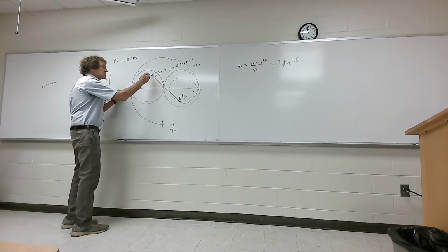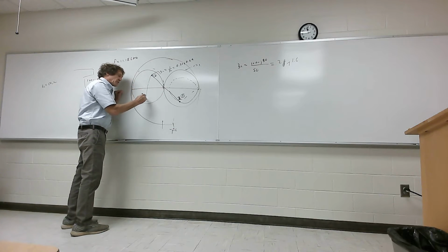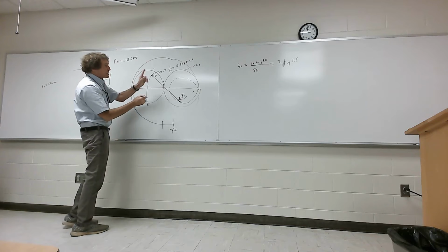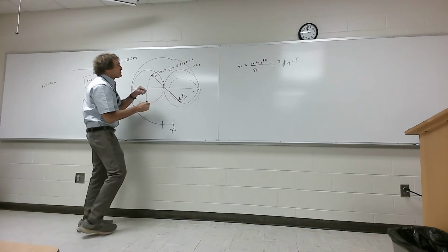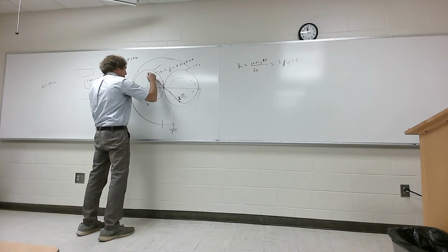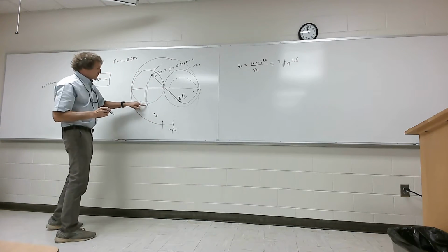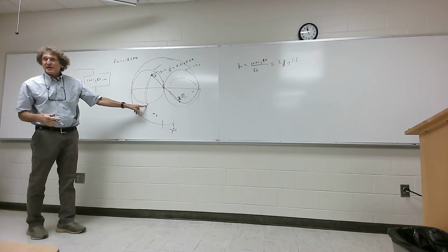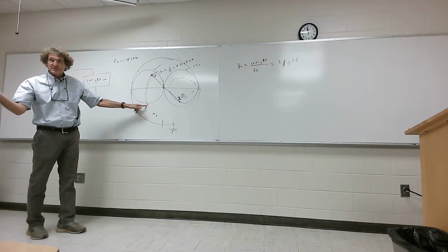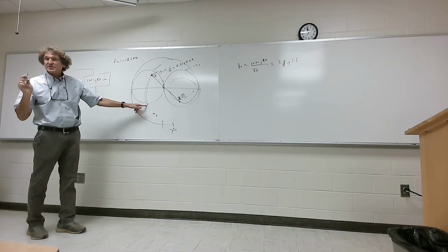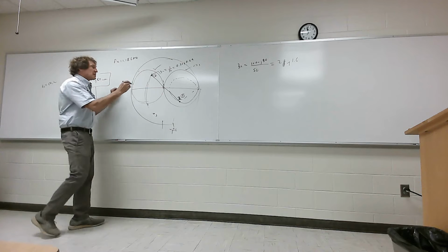I'm here, I can go two ways. If I go this way to this point, remember I'm going to be on the 0.3 circle right here. It would be 0.3. If I go this way, I have to add negative admittance, correct? That would be an inductor. That would be in parallel. That would be bad. Follow me the way he stated. He wants an inductor in series, a capacitor. So we're going to go this way.